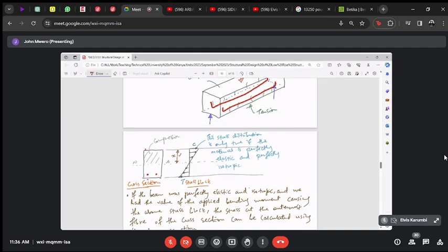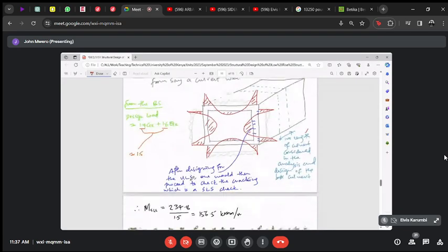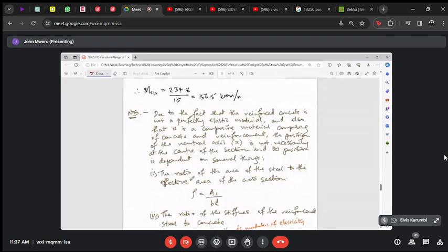But the material we're dealing with, concrete, itself is not perfectly elastic. It's actually elastic plastic. And then we have put in reinforcements. So again, changing that scenario a little bit further, we will need to calculate where the depth of that value x is in our section. And don't worry, I'll sketch this section for you and we will calculate these numbers, and you will see that it's not a difficult thing to calculate.